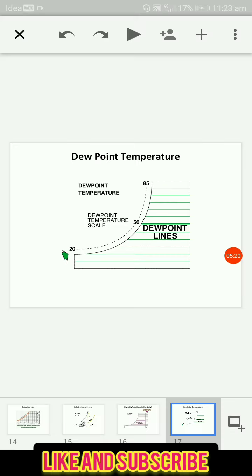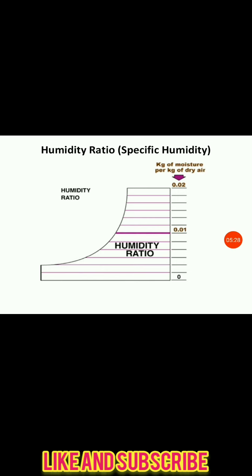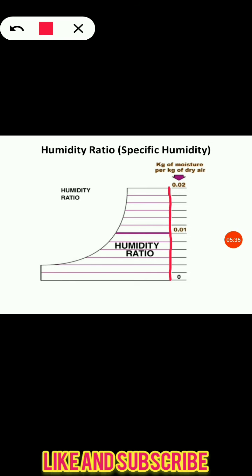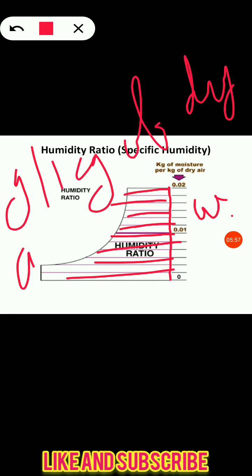Next is the specific humidity lines. On your screen you can see a specific humidity line. Specific humidity is represented by omega. Here you can see horizontal lines; these are called specific humidity lines, and generally it is measured in gram per kg of dry air.